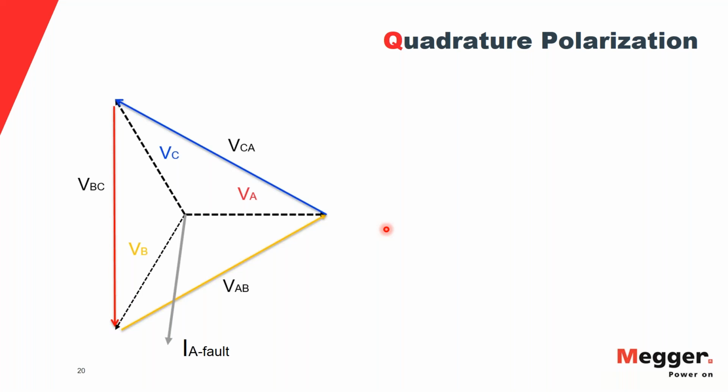So this is a very good design used in many of the directional relays, where they sense the other phases for voltage and keep that as a reference. Now, why do we call that quadrature? Quadrature is nothing but 1 by 4, right? In the reference plane, you have 360 degrees multiplied by 1 by 4, so you have 90 degrees. So this is nothing but a 90-degree connection, right? So what exactly is the 90-degree connection? The 90-degree angle is between your phase A voltage and the polarizing voltage. You see, I have 90 degrees between my line-to-line voltage and line-to-neutral voltage.